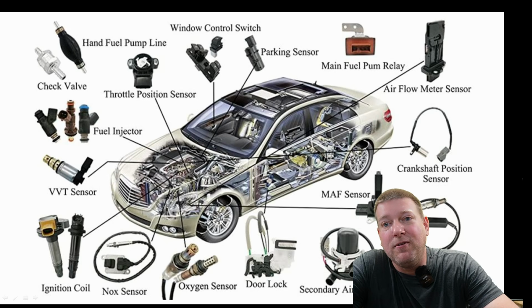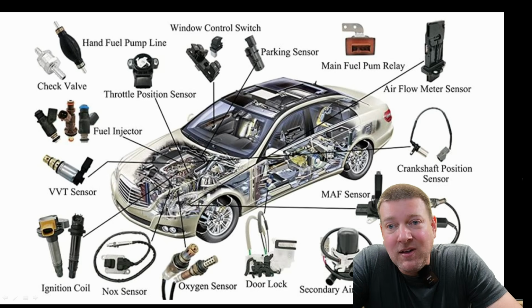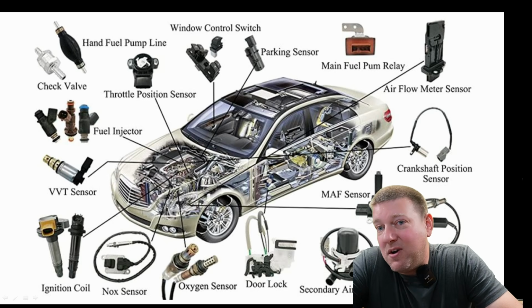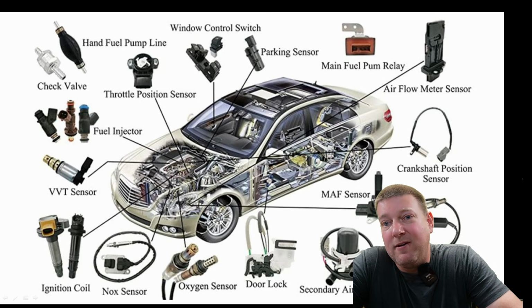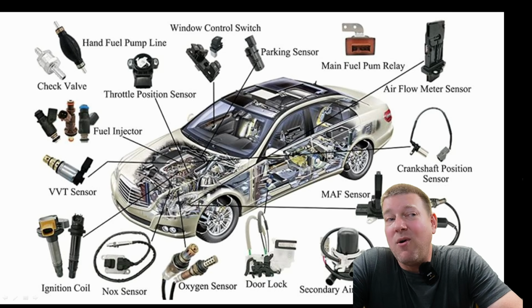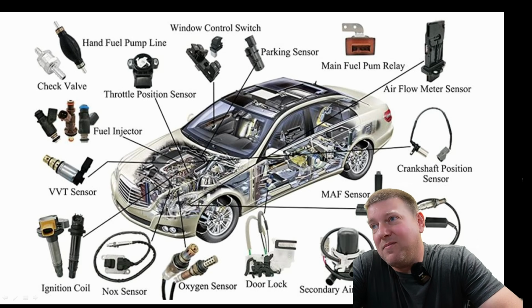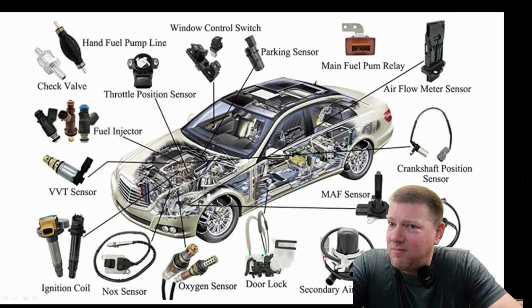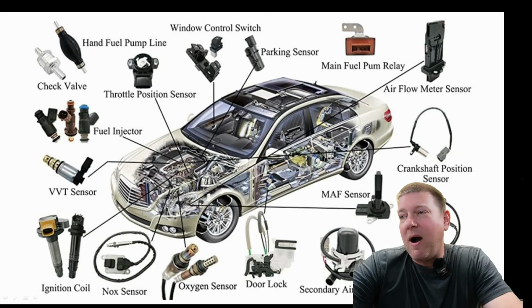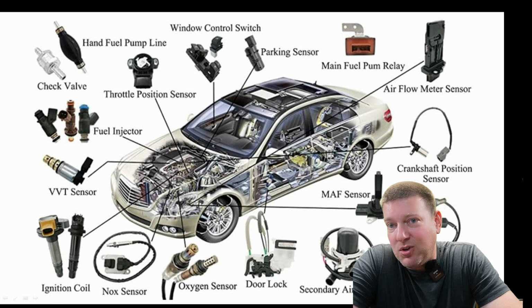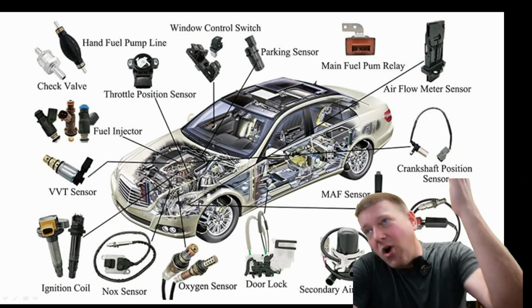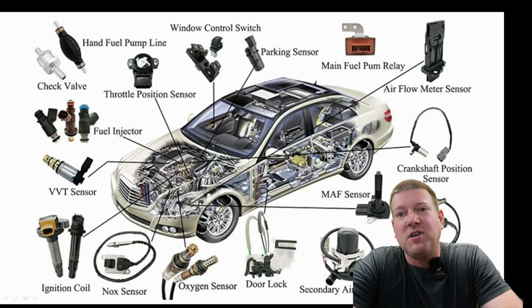We can account for even things like emissions or knock if you're using the incorrect grade of fuel. We can now automatically adjust the engine for that without blowing the engine up. It's pretty cool stuff. You won't get the same amount of power, but it usually won't blow up the engine. That's all because all these devices talk to each other.